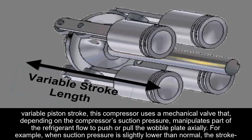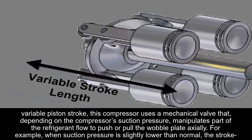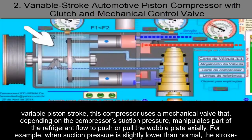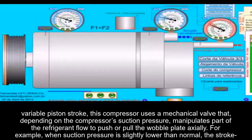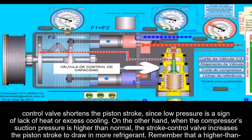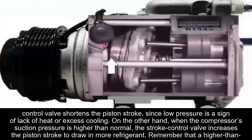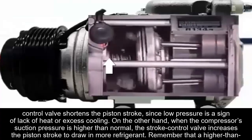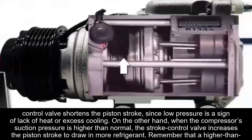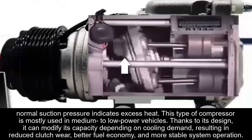To achieve variable piston stroke, this compressor uses a mechanical valve that, depending on the compressor's suction pressure, manipulates part of the refrigerant flow to push or pull the wobble plate axially. For example, when suction pressure is slightly lower than normal, the stroke control valve shortens the piston stroke, since low pressure is a sign of lack of heat or excess cooling. On the other hand, when the compressor's suction pressure is higher than normal, the stroke control valve increases the piston stroke to draw in more refrigerant gas. Remember that a higher than normal suction pressure indicates excess heat.